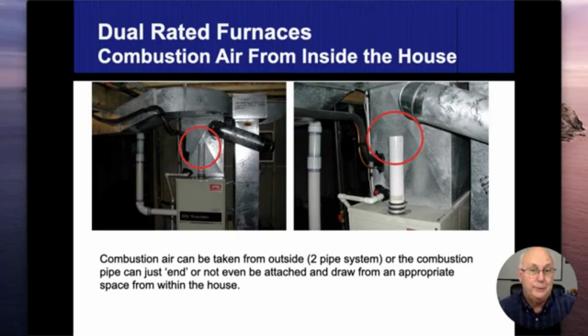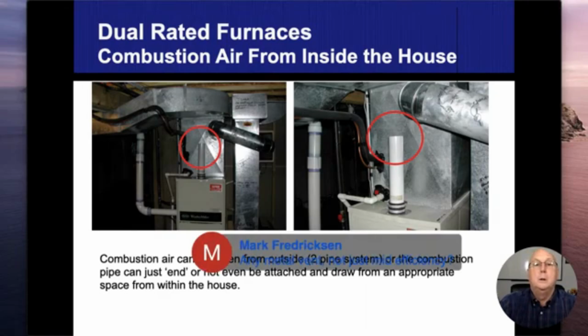So I may have mentioned before about bringing combustion air from the inside. This high efficiency furnace can operate this way if I'm in a wide open basement. It can't be in a bedroom or a bathroom; you can't draw that combustion air from the bedroom or the bathroom. It needs to be big enough, depending on the BTUs that are there, to get enough combustion air. And quite frankly, now I'm taking conditioned air and bringing that to the outside. Let's see what this is here. So any metal vent, not just mid efficiency.